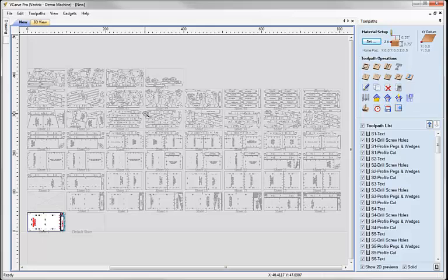Okay, so there we have it. We've created all the toolpaths for all 52 sheets. We've created dog bones for all the parts. We've made an allowance for the internal slots, so if there's variation in the material thickness, we can account for that by increasing that allowance slightly. And there's been no human intervention, no opportunity for mistakes. We've also importantly created the single outer boundaries for those components that were actually created for multiple components. So that's it, and thank you very much for listening.